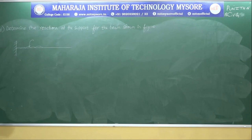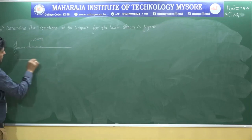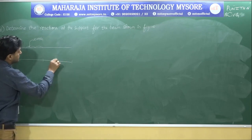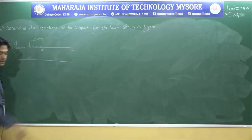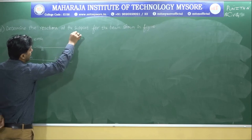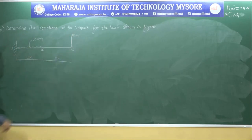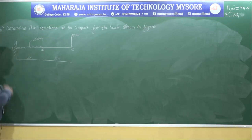So the UDL that is acting, they have given it as 10 kilonewton per meter. So the span they have given is, this is 2 meter and this is 2 meter. This they have called it as A, this point is B and this point is C. So at the end there is one more point load acting, that is 10 kilonewton. Now they are asking us to calculate the reactions at the supports.